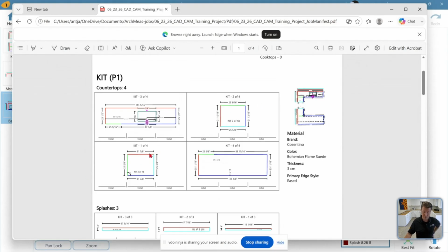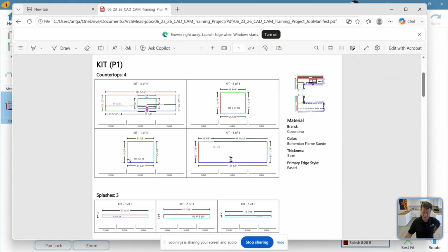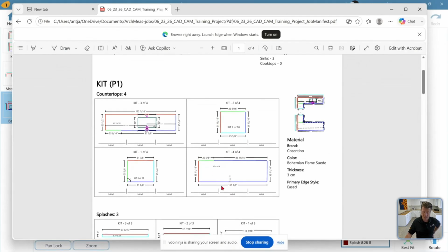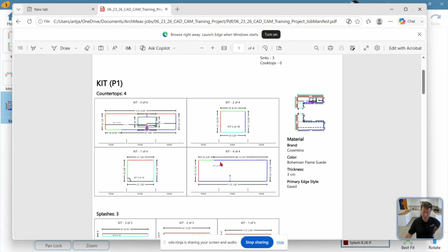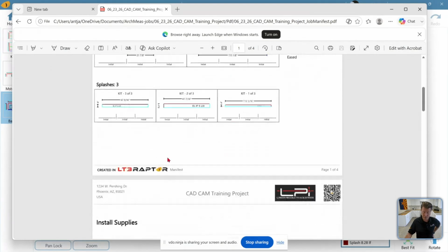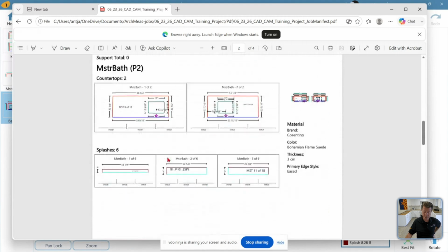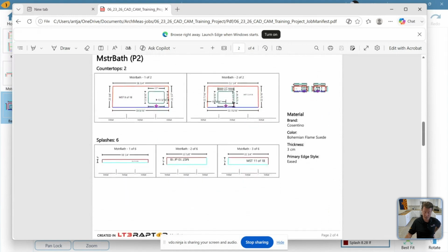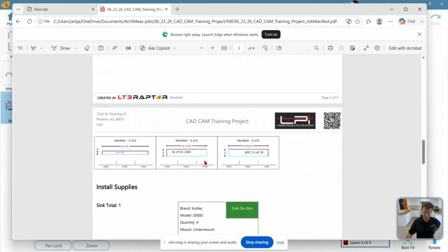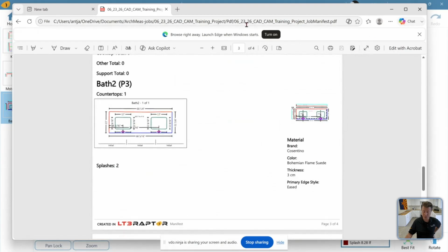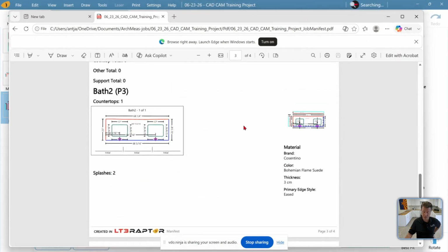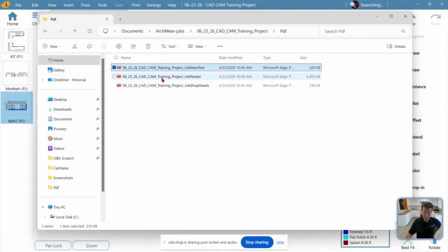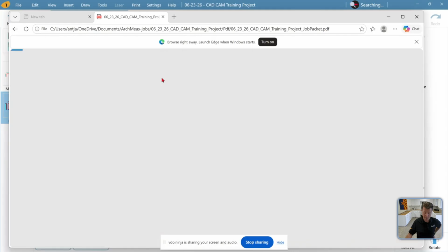It'll auto dimension the exterior, okay? If I have a dimension on the inside, this is that peninsula, right? I put a parallel dimension that shows it has a 10-inch overhang. Right? So that dimension's right there. This is just a list. And the way I have it set right now, per page, it'll list all those parts. Okay, so this is kind of useful, especially as you're gathering all the parts for a big project.